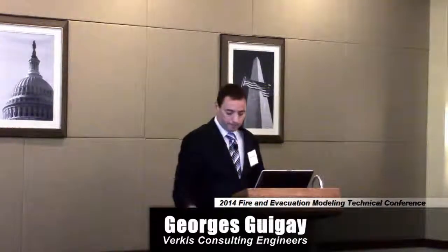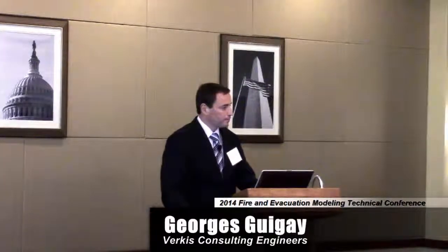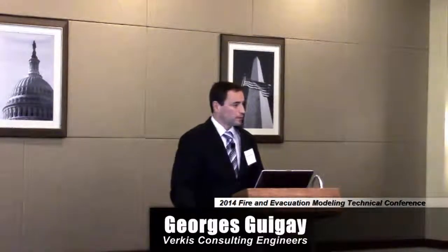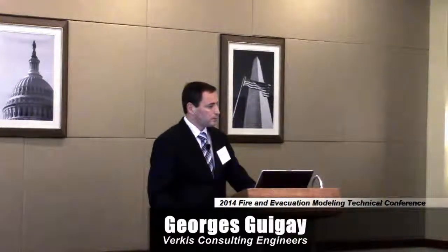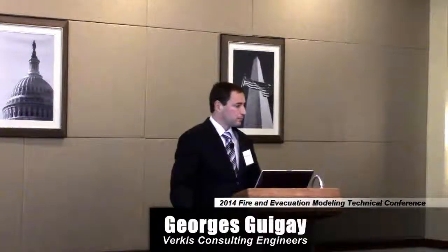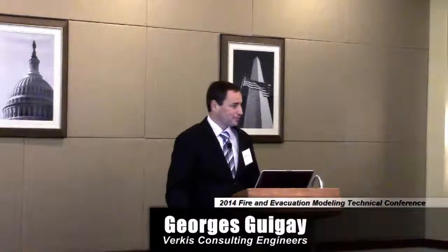It's hard to say case by case whether it's more conservative or less conservative. I think you can say that when you're dealing with situations like this where you have a relatively coarse grid, because inevitably you're doing this huge stadium, so your grid is this big on the fire. In FDS6, we're using what we consider to be a better turbulence model. So we get what I think is a more realistic plume, which entrains more air and dilutes more, which may explain why his layer came down a little further. If you look at old calculations with FDS4 and FDS5, if you had a really crude grid, you would see the smoke go straight up instead of meandering like a real smoke plume would. So with FDS6, I think we're doing better with the smoke plume dynamics.